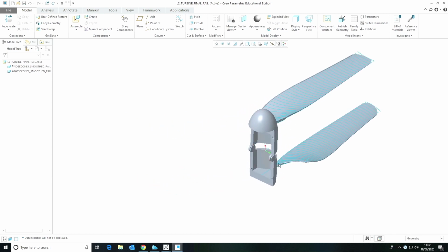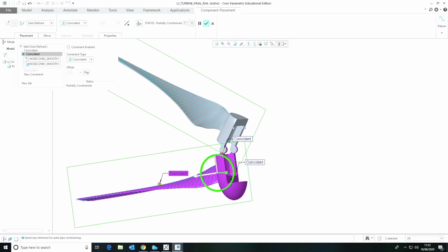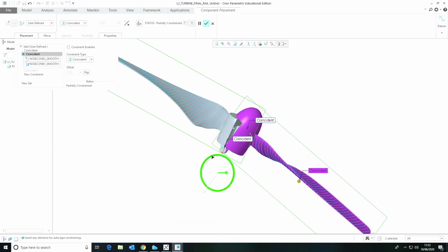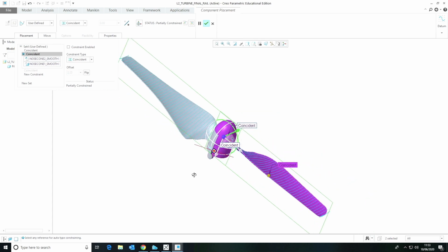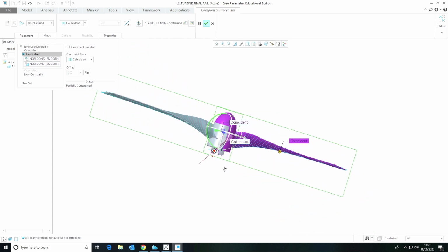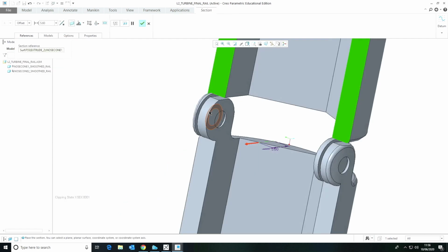Both halves of the nose cone were folded together via a built-in hinge and glued after printing. A set of teeth on the mating surface located both halves. Splitting the nose cone at a right angle created more contact surface area and kept the main incident surface of the nose cone smooth to reduce drag.